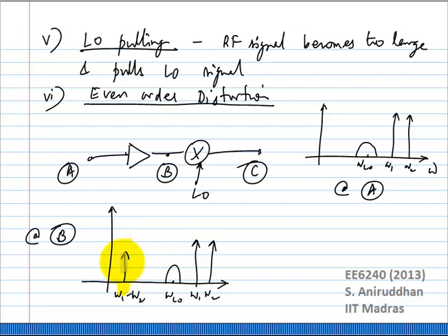But really the biggest problem is the DC offset problem. Whether it's caused by self-mixing, interferer leakage, or something else, that is really the biggest problem. Now the DC offset can also be time varying. But you should realize that this is actually a very big problem.